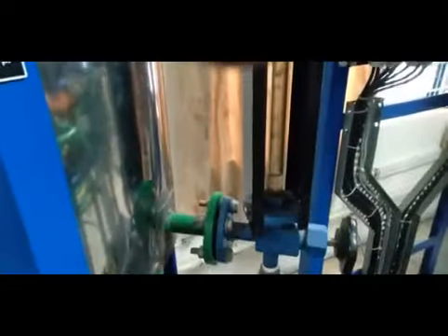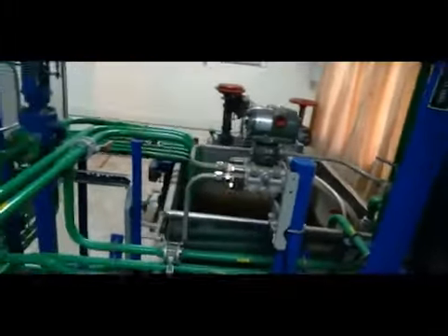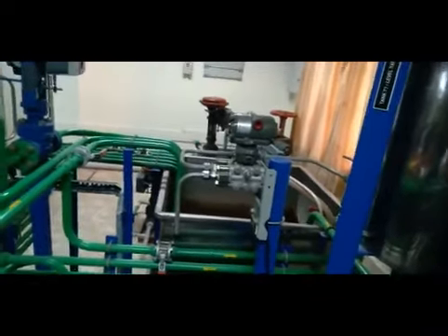We can see that water level coming up in this glass tube indicator. There is a manometer we have. Based on the level changes, you can see that the current coming out from this particular DPT is changing. This DPT is connected with the DCS, so that we will make control actions, and flow to this particular control valve is controlled, right?